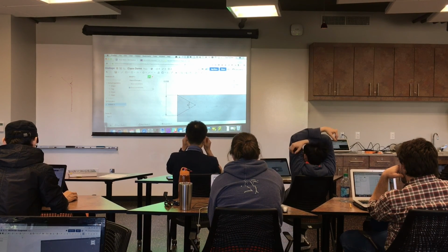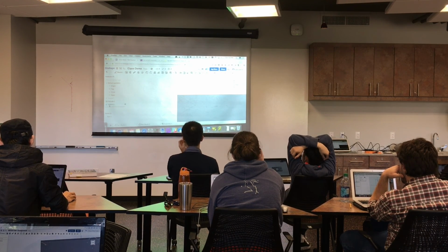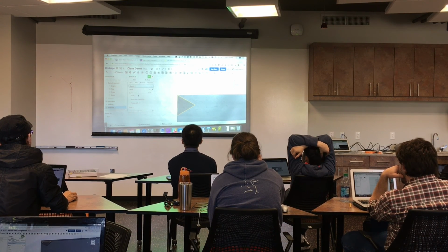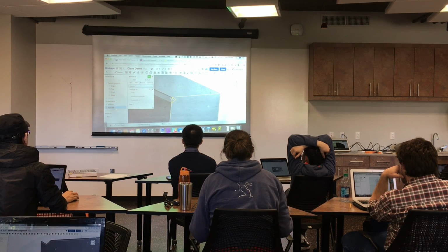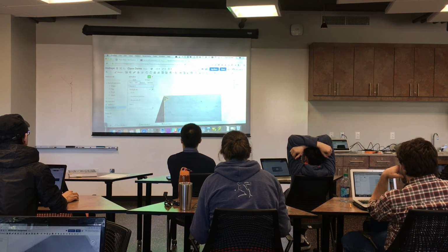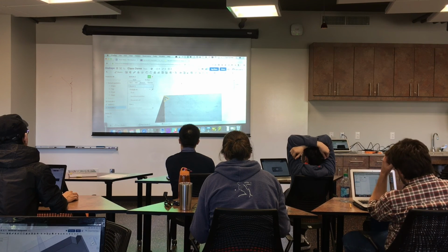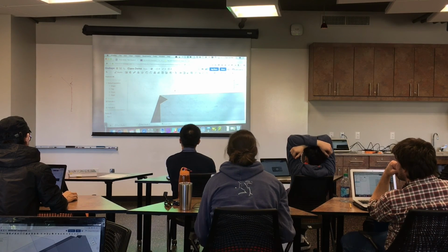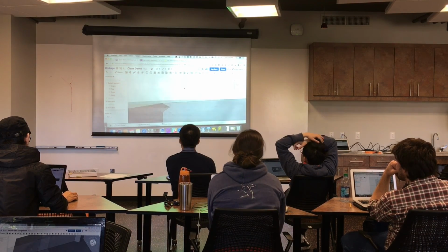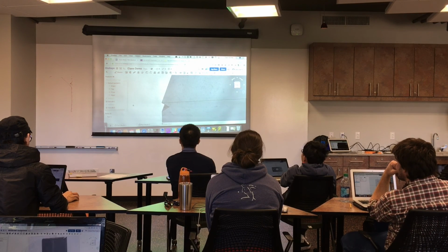I'm going to click check. I'm going to select that sketch. I'm going to extrude, remove, and I'm going to say through all. So now if I look, I have 1 tooth cut into the block. So only 150 more to go. And you don't want to do that manually. That would be horrible. If you have to do something more than a couple times, there's probably a better way to do it in CAD.